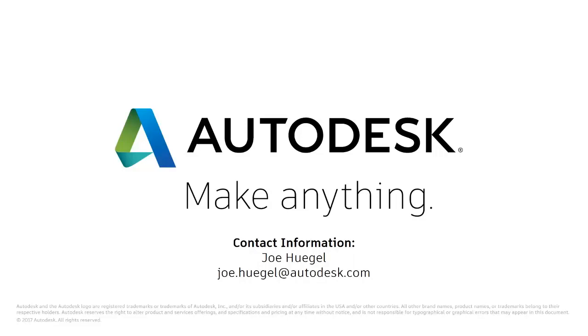Yeah, so specifically to answer that question, there's a handful of ways that Moldflow can use different geometry. So whether you're using a design from part only and you want to build your mold inserts in Moldflow, we have the ability to do that. We also have the ability to import your entire mold assembly if you would like to, or you can just select specific components or specific inserts that maybe are made from a different mold material to import and represent at that mold material. So I guess to answer the question, we have the ability to model components inside the software as well as import 3D geometry from a mold design.